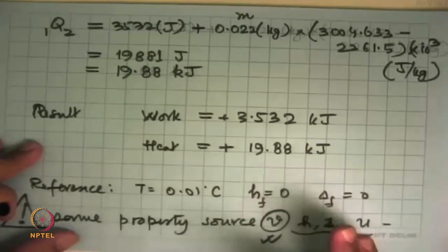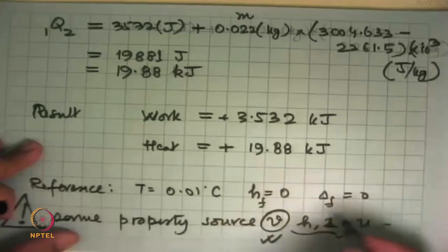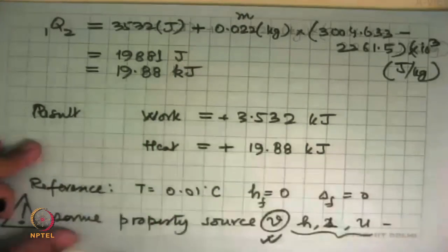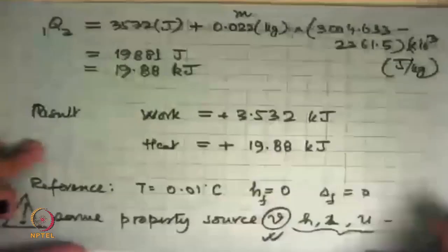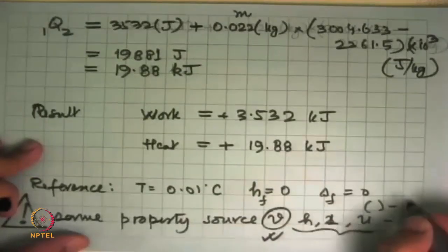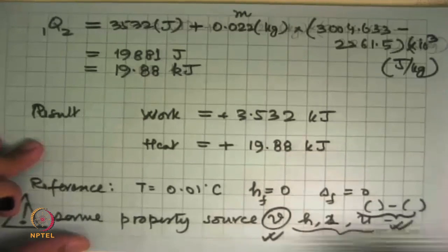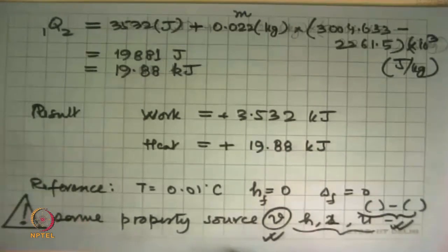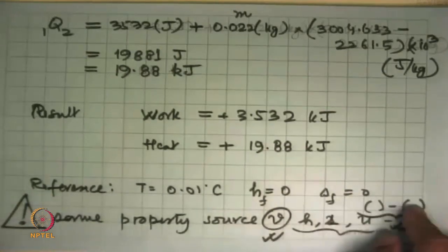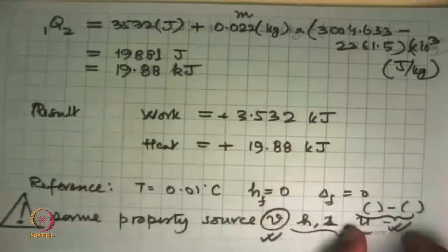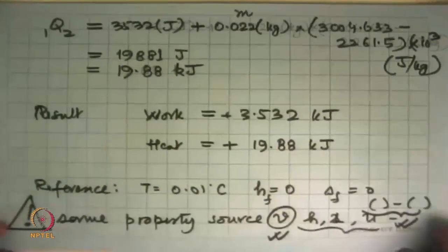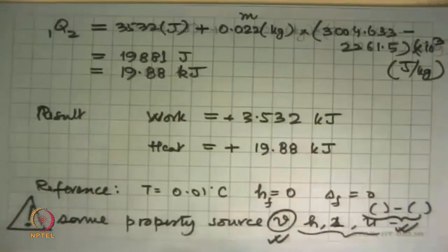These will be different, but don't worry too much about it, because in most of the problems, whether it is heat transfer or work transfer or say a throttling process, we are always dealing with the difference of two properties, and the difference of two properties will be pretty much close to one another irrespective of what the reference temperature was. So you could have slightly different values of individual properties, but the difference in the properties will not vary very much. So don't worry too much about it at that point. The difference should be matching with what we have.